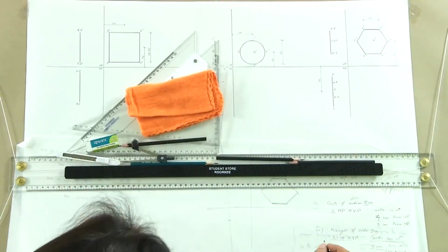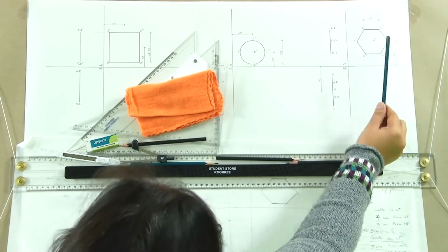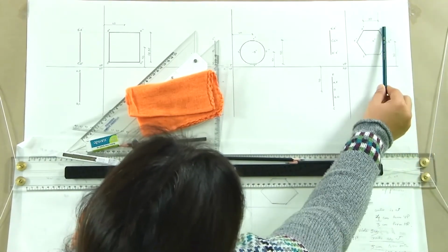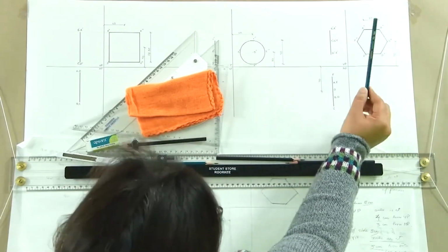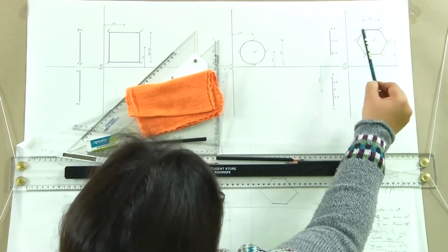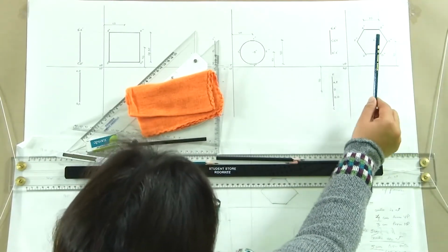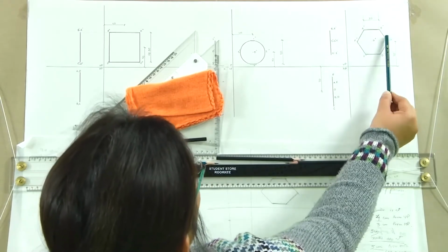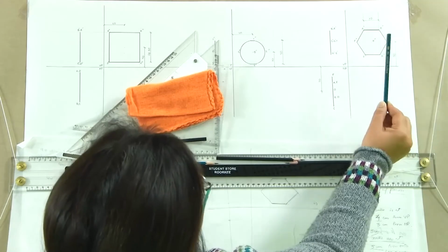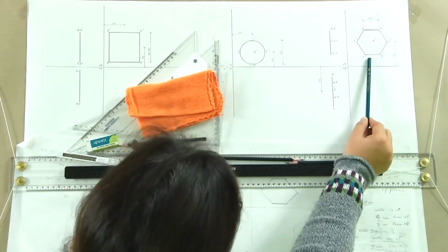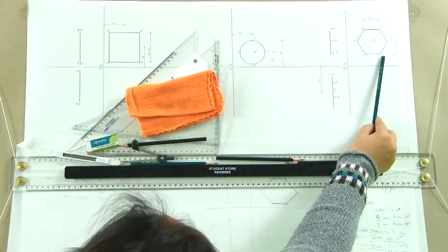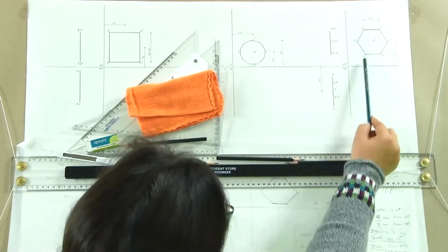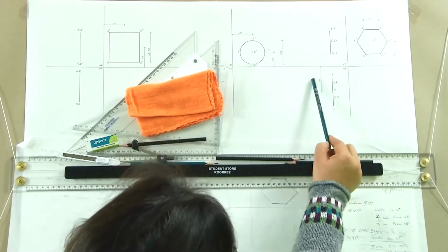Another condition which was given, that the hexagon has two sides parallel to HP. So, we took it parallel to HP. If it was perpendicular to HP or parallel to VP, we would have got a hexagon which would have two sides perpendicular to HP like this. In this condition, this is the hexagon. Once we have drawn the hexagon, we will take the projections onto the VP and then HP.